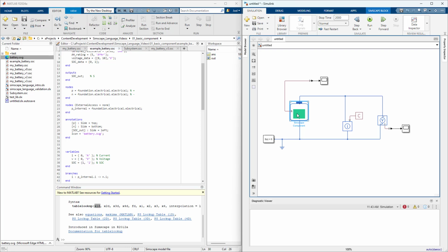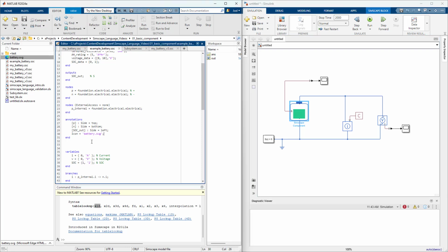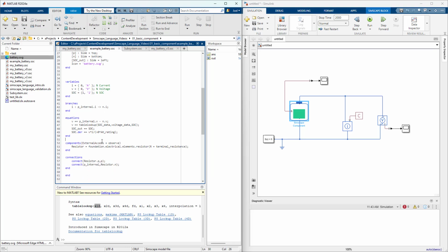There's some things with mode charts where if you want really complex behavior, and we'll go over that, and there's things like multi-domain models where we're going to do not just electrical, where there's additional Simscape language features that are relevant. But the most important thing that I taught you today, you may not realize it, but it is just this table lookup.